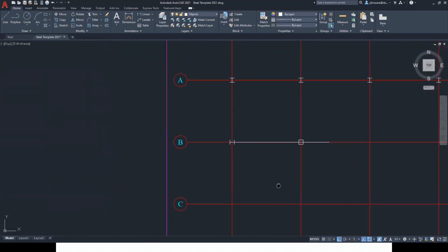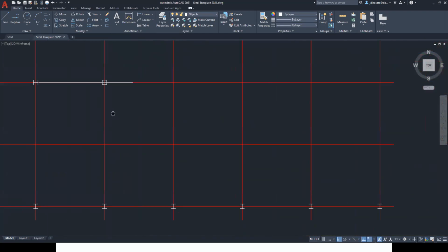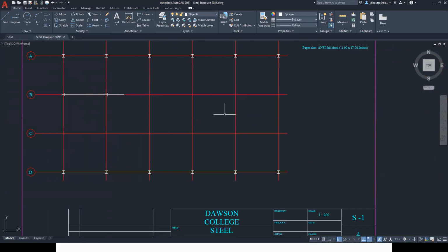And then, of course, once you've done all your beams on this side, you simply take them, copy them with the columns, and put them on here. So you work on this, and then you copy them down here. This way, it's all done. Understand? And then you start putting in your joists and so on. As soon as one is ready, if this thing was pretty much symmetric, I would even use the array command to put in all the joists if I wanted to. But it's up to you.